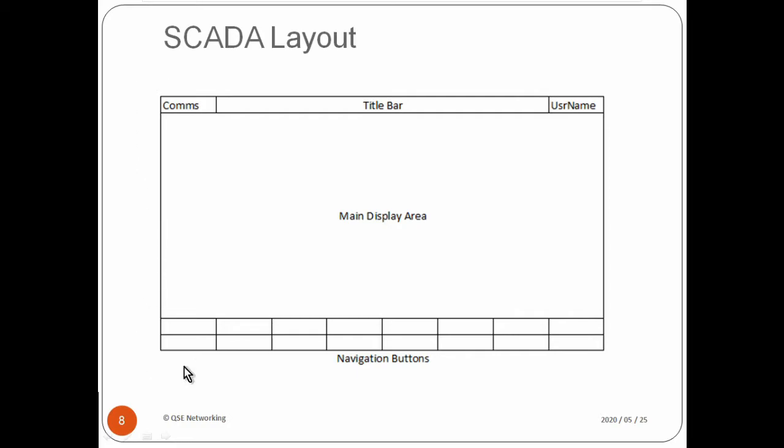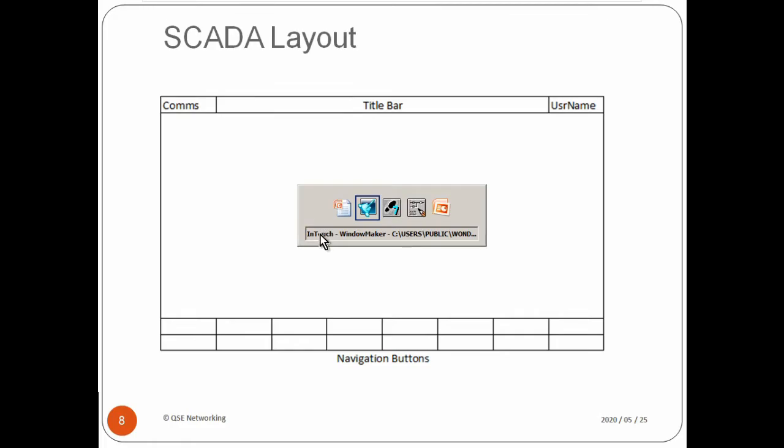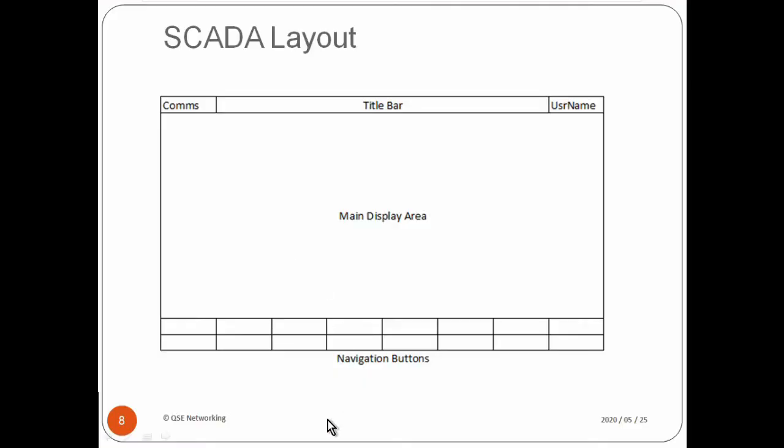You see now, actually, this is a standard format which we normally use, because remember, you might have 20 area displays. You might have detail displays, etc. And you've then got to create navigation buttons on every one of them to go from screen to screen. So we normally put a general navigation bar down the bottom with some buttons, which allow us to mark this as area 1, 2, 3, 4, 5, and if you click on it, it doesn't matter what is on the screen, you then go direct to that screen.